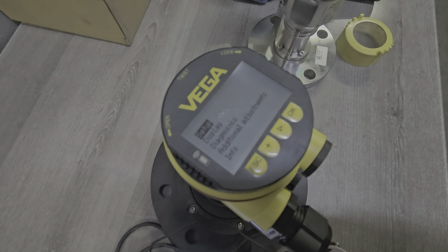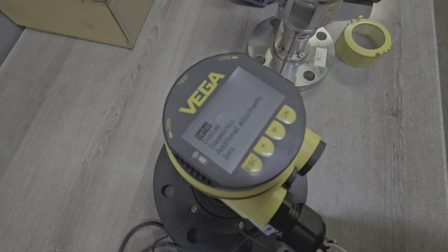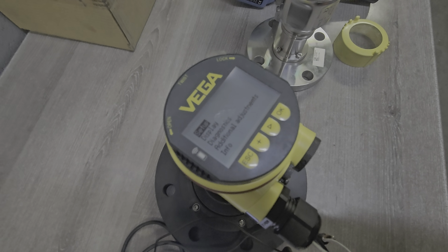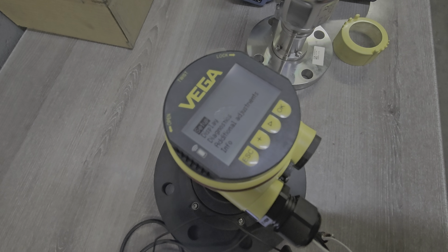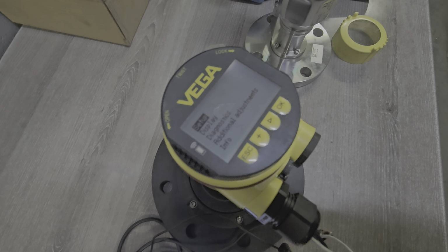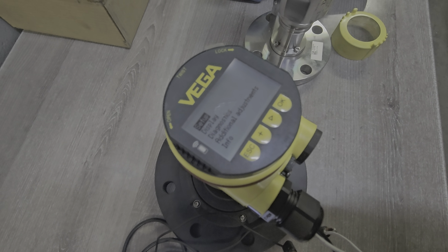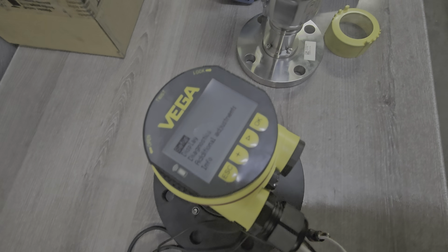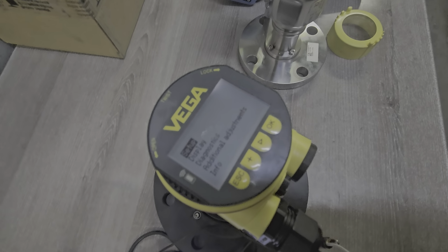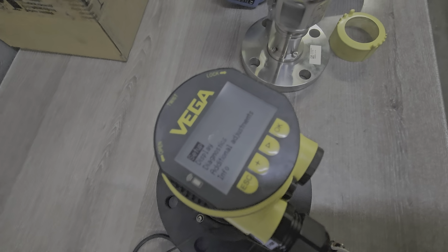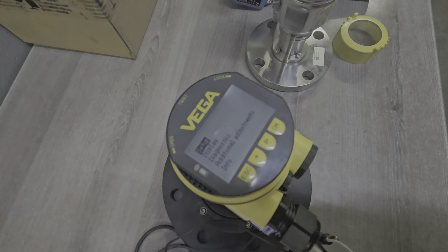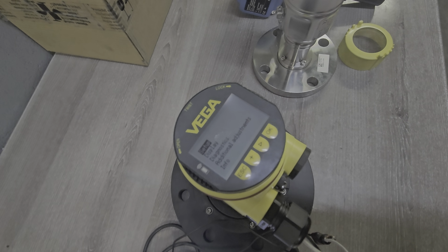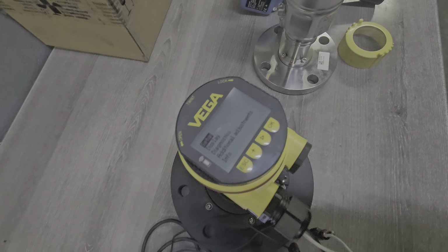Under diagnostics, you are getting errors. If an instrument is in a fault state, when you enter diagnostics, you're going to find errors there. And then you've got additional adjustments where you can do things like damping, filtering. If you want to set up how long you want the instrument to update. Sometimes you want the instrument to update immediately, but sometimes you want the instrument not to be too noisy, meaning when you damp it a bit, it updates every 2 seconds or those kind of things.